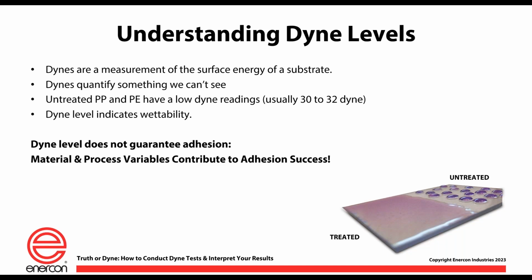And really what the dyne level is indicating here is wettability. So you really have to get these terms contexted in your mind. Dyne level is really indicating a wettability condition. It does not guarantee or ensure that you're going to get an adhesion benefit.